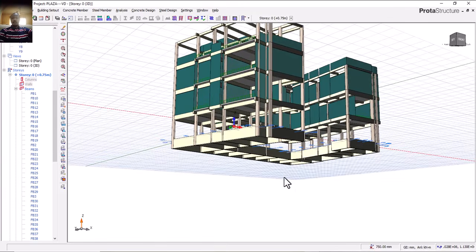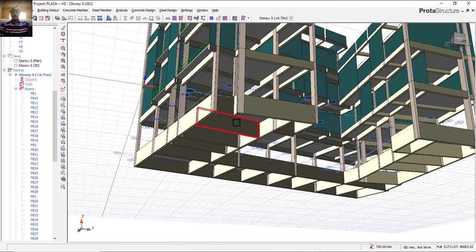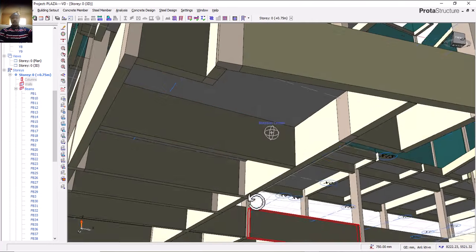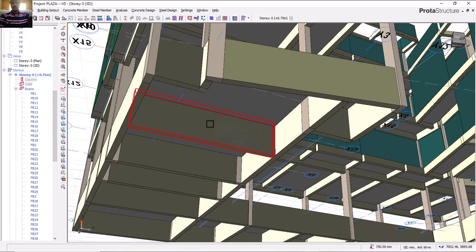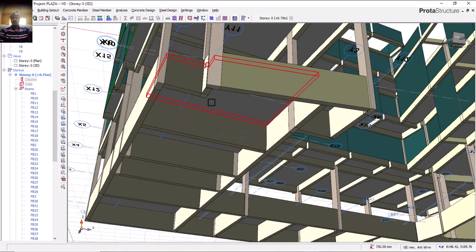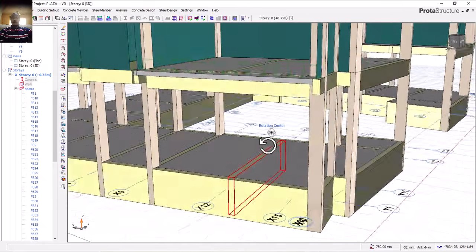Is that okay? So you can now see that place that we are going to be backfilling. You backfill under here. When you backfill it up to this level and compact it properly, is that okay? To remove all the voids. So now what next? The remaining 175 will be this slab. As you can see it here.